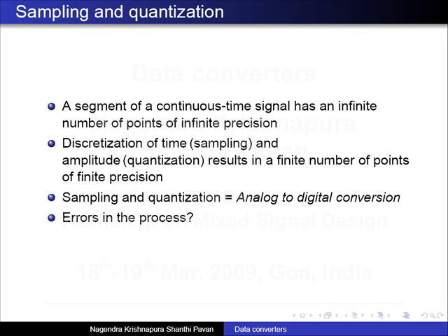And then you quantize the amplitude also, that is you let it take on only some amplitude values. Then if you take a finite segment, let's say my speaking this sentence, you will end up with a finite number of points. That's why it is convenient for storage. It's very hard to store a continuous time signal because there are an infinite number of points. Whereas here, if you sample it along the time axis and also quantize it along the y-axis, if you take this length of speech, you will have a finite number of points. That's the main reason why we do that.